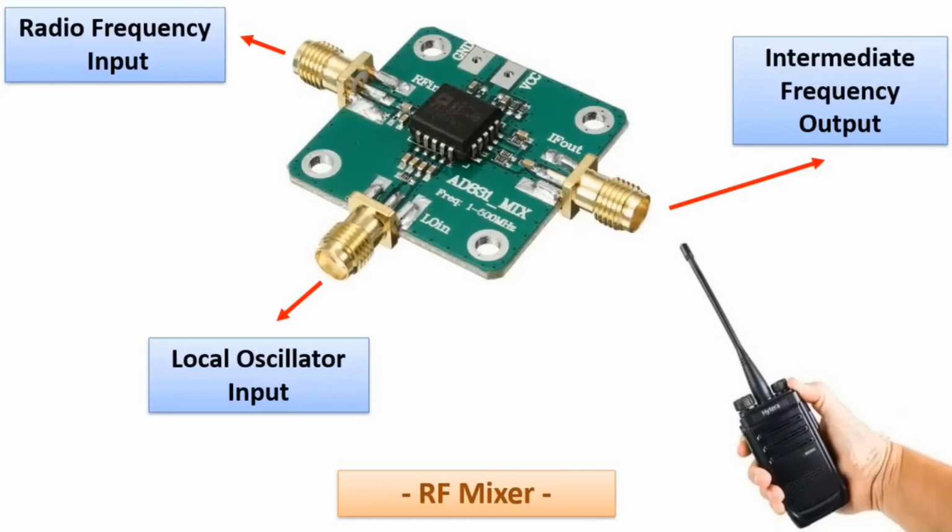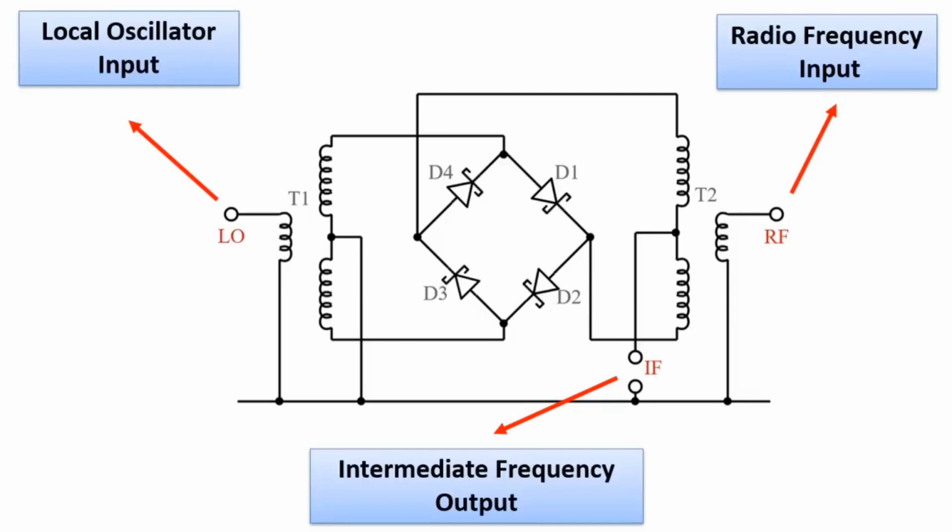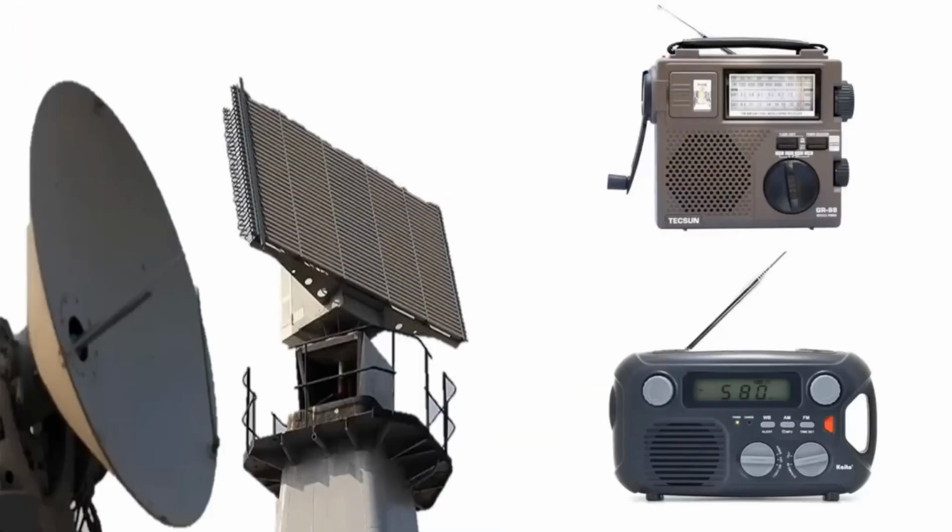Schottky diodes are used in RF mixer circuits used to move the frequency of a signal from one band to another band. When we look at the circuit diagram, we can see that there are 4 Schottky diodes in the full-wave rectifier structure in this way. Thanks to the RF mixer, the incoming audio signal is encrypted and sent to another receiver at a different frequency value. In addition, these RF mixers are used in circuits wherever radio frequency signals are used, from radio receivers to radio transmitters to radar systems.